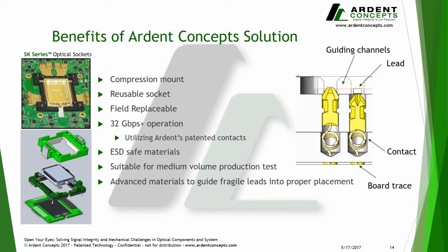One of the key advantages of our design here, on the right, is that you can see how we carefully guide those fragile leads into contact with our contact technologies. This can be a problem because in production test environments, you need to assemble this package, test it quickly, and then put it into its final environment without damaging it in between. So we worked hard to develop special guiding channels to make sure that there was no damage done to the package during this process.